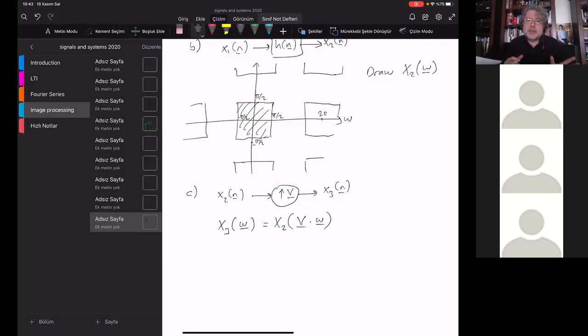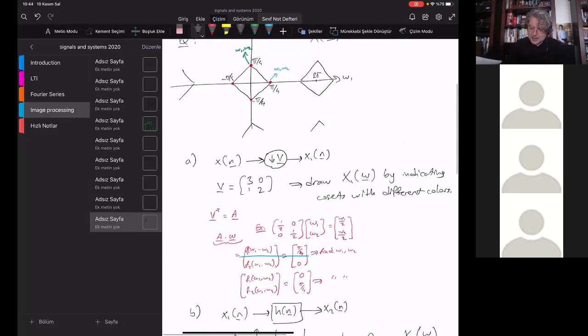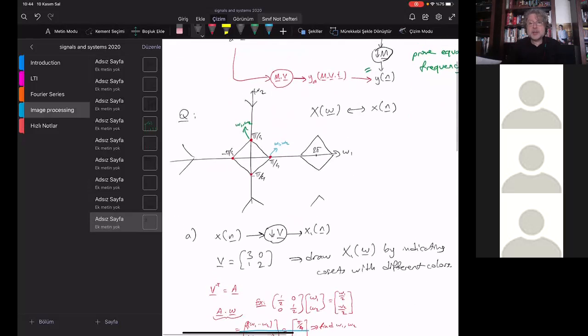I didn't tell you this formula because we have seen it in one-dimensional case already. In 2 dimensions, it's simply like this. Originally, we were dividing by V, or we were multiplying with V inverse transpose. It was V inverse transpose times omega. Now it is V times omega, and there's no summation or any extra terms. This thing makes everything to become smaller, but while becoming smaller, those 2 pi by 2 pi periodic extensions will now become smaller periodicity. It will eventually also be 2 pi by 2 pi periodic, but the shape that we have originally in the question, this shape, will contain some extra components. Or there are 5 more extra components that are fitting inside this tile. And by the way, the shape will be transformed back to the diamond.